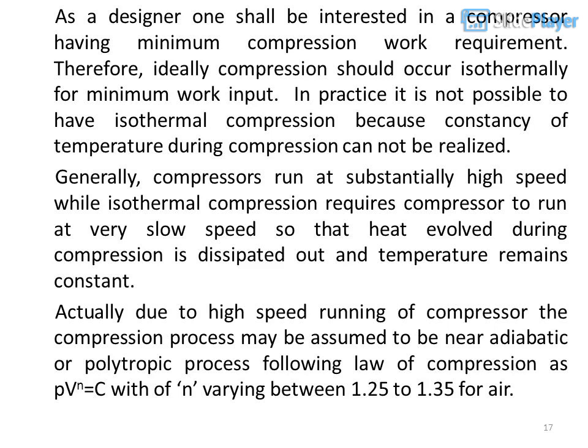Generally, compressors run at substantially high speed, while isothermal compression requires the compressor to run at very slow speeds so that heat evolved during compression is dissipated and temperature remains constant. Actually, due to high-speed running of the compressor, the compression process may be assumed to be near adiabatic or polytropic, following the law of compression PV^n = C, with n varying between 1.25 to 1.35 for air.